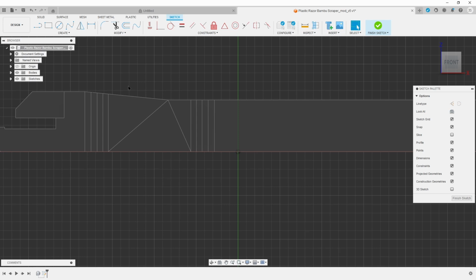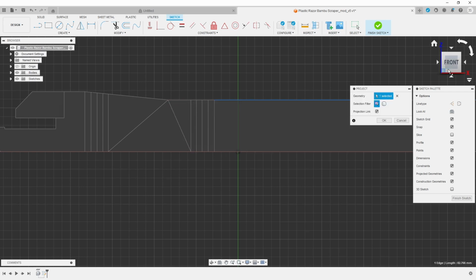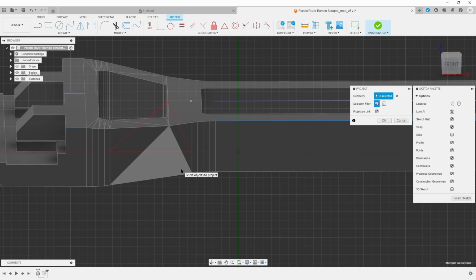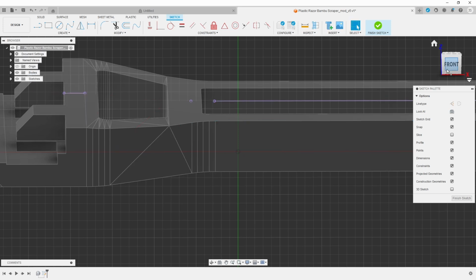The first thing I want to do is this particular file has a very gentle slope in the z-axis. Those don't print very well. The problem is that in the z-axis, slopes end up being stair steps. And so if your slope is too gentle, you see a very spread out stair step.